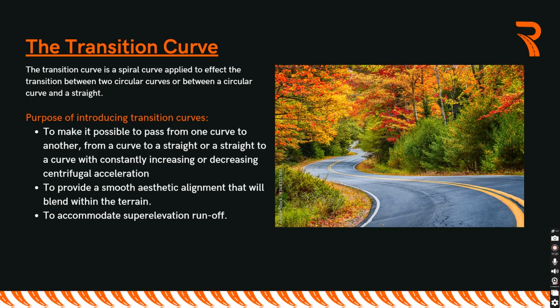The other one is it makes it possible for you to pass from one curve to another, from a curve to a straight, or a straight to a curve with constantly increasing or decreasing centrifugal acceleration. Because ideally, centrifugal forces will be acting on any vehicle that is negotiating a corner or a curve.